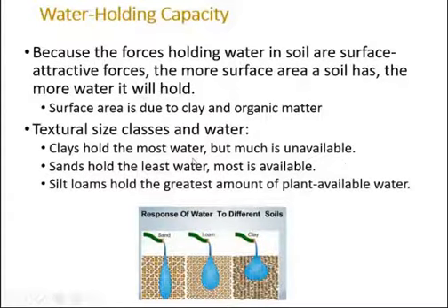Clay and organic matter increase the surface area, and what we can see is that clay soil will hold more water. But is that water available for the plant? Well, much of that water will not be available, because it is held tightly in the small pores of the clay. Sand holds less water, but it is available because the plant can take it. It's not held tightly in the soil. However, the sand would lose the water very fast, so you would have to irrigate more frequently.